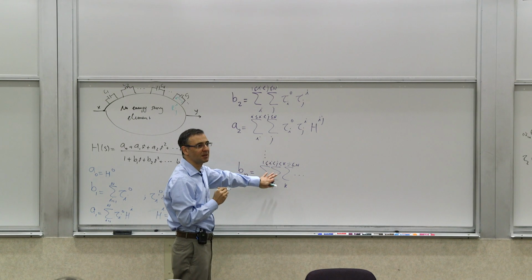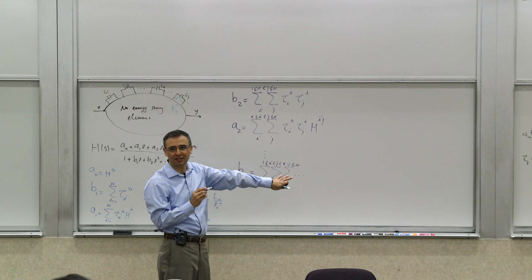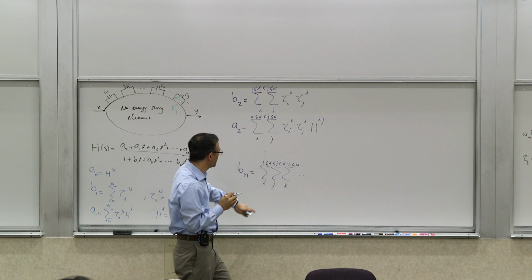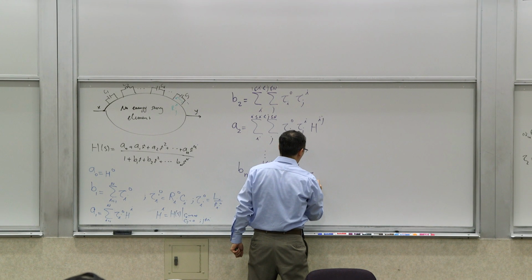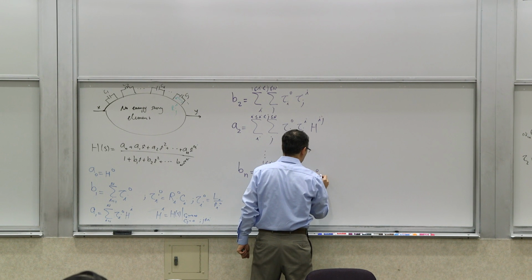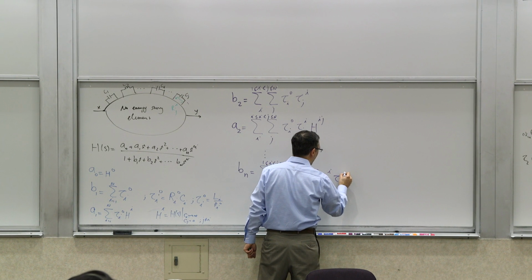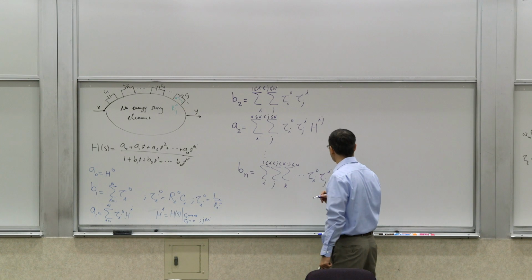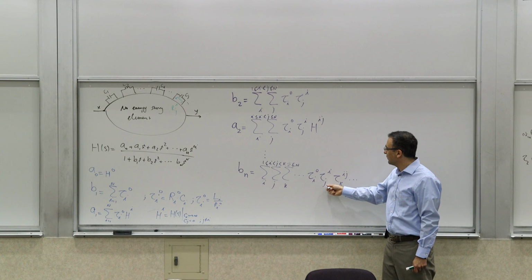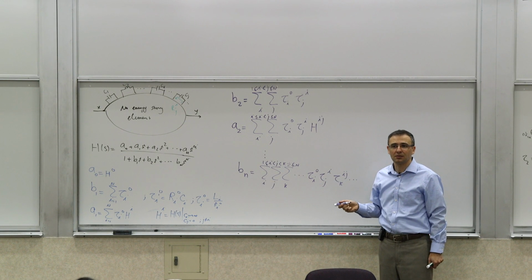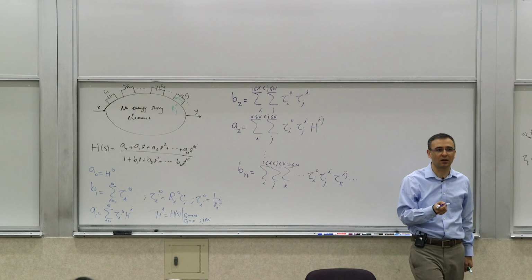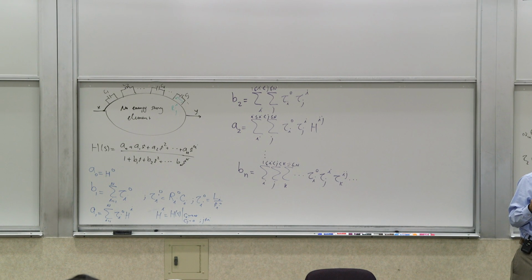This looks messy, but it's actually not as bad when you start calculating these things. And then the product of these time constants, tau i0, tau ji, tau kij, etc. Remember, you will always have only one subscript for these taus, but you can have multiple superscripts, because the superscripts are the indices of elements that are infinite valued.